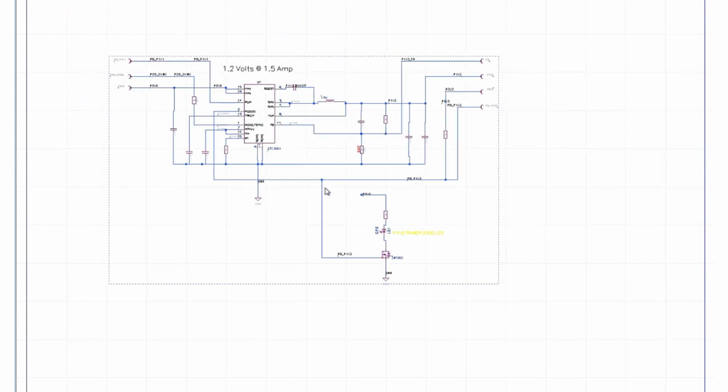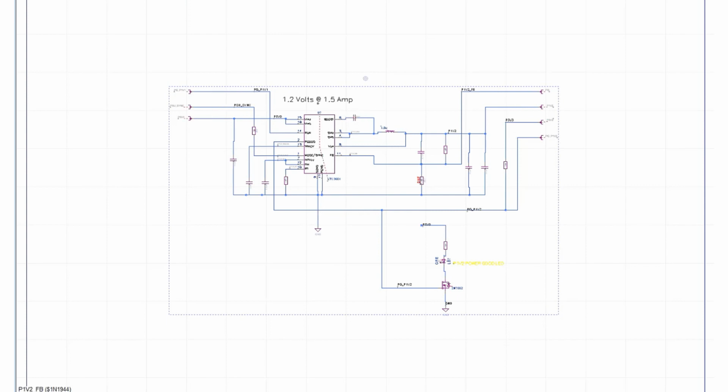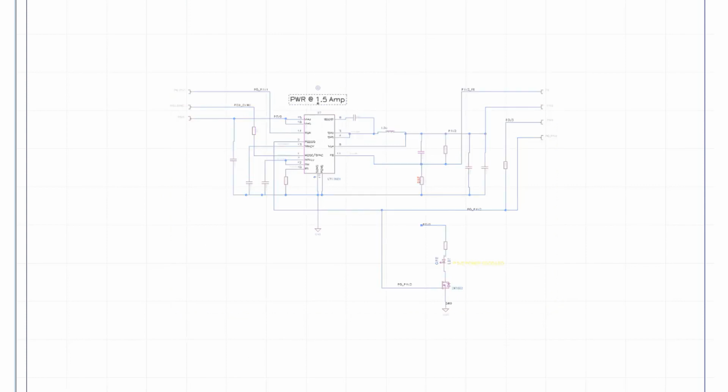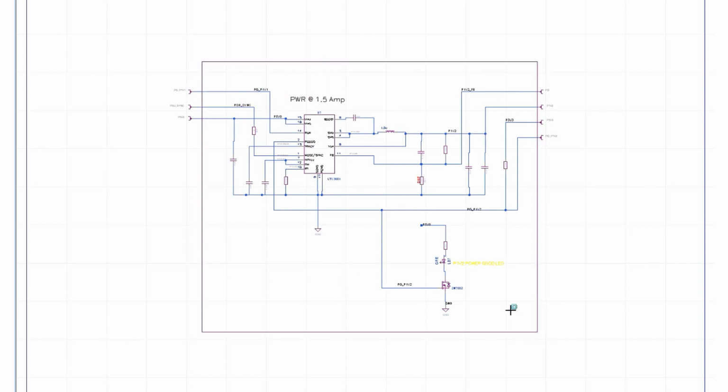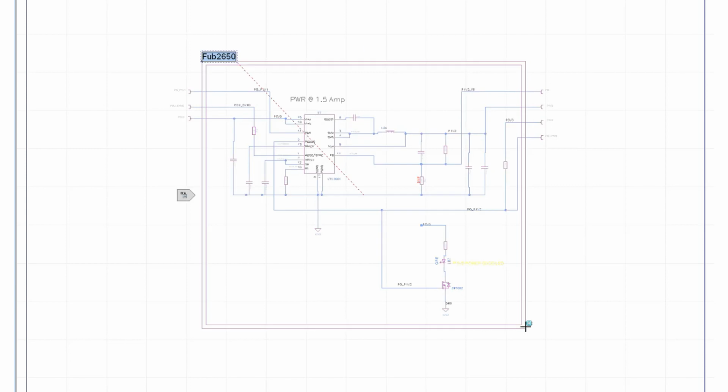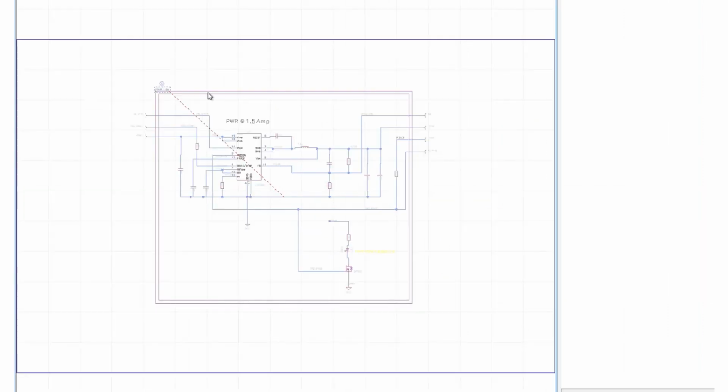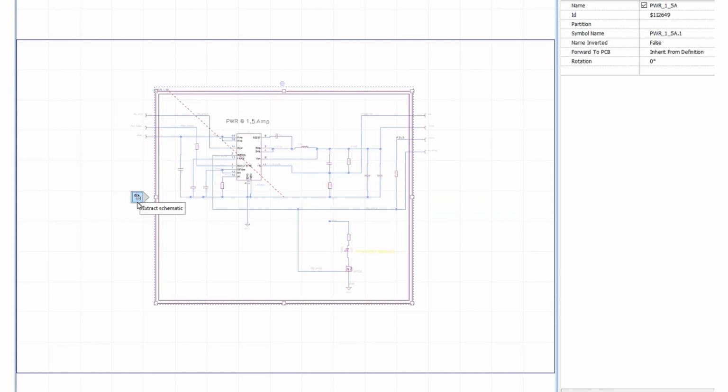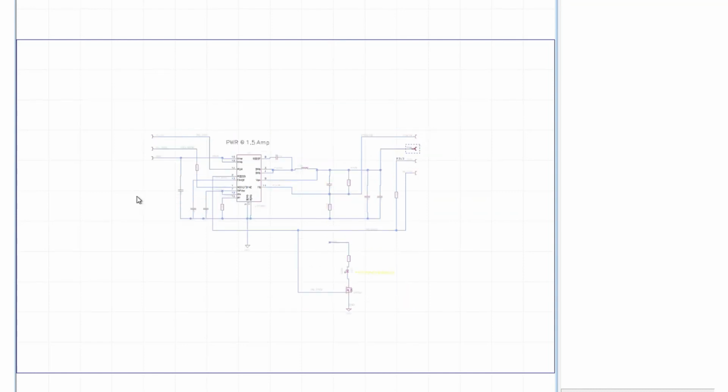Then I will paste the logic circuit into a new schematic project. I'm going to modify any text references of the previous circuit to something generic. I will now capture a block boundary, change the name for the block to a generic name, then extract to push the circuit to another schematic sheet.